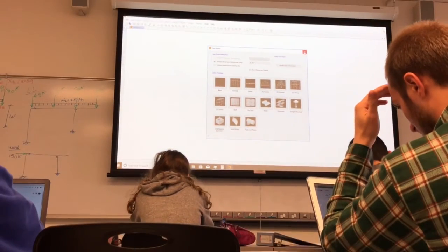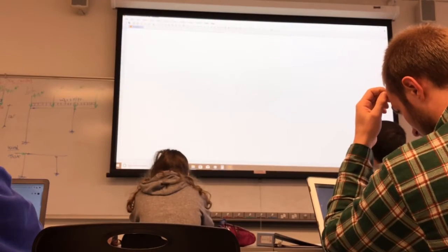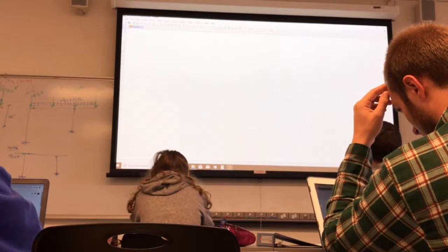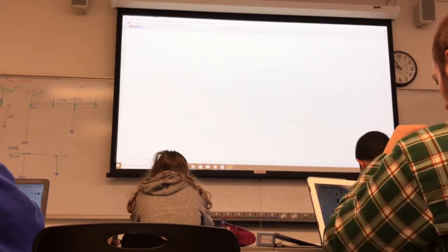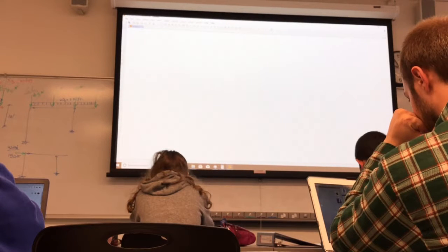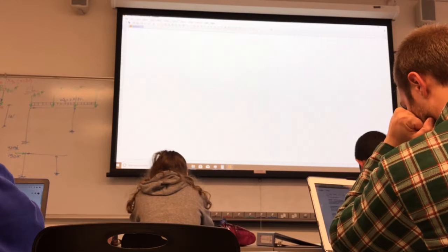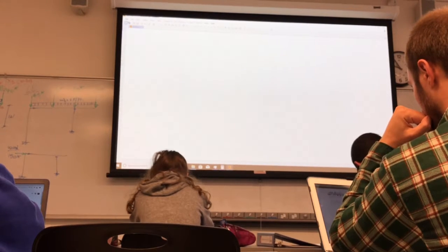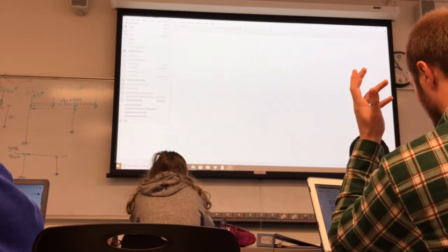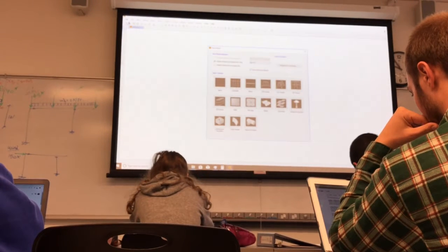So actually before I do that, I'm gonna go here, change the units. It gives you all kinds of units you can imagine, the kilograms, meters, newtons, tons. So we want Kip foot, so we go with the Kip foot. And you can change it anytime during the analysis. So I go to File, New Model, and it's now Kip foot.